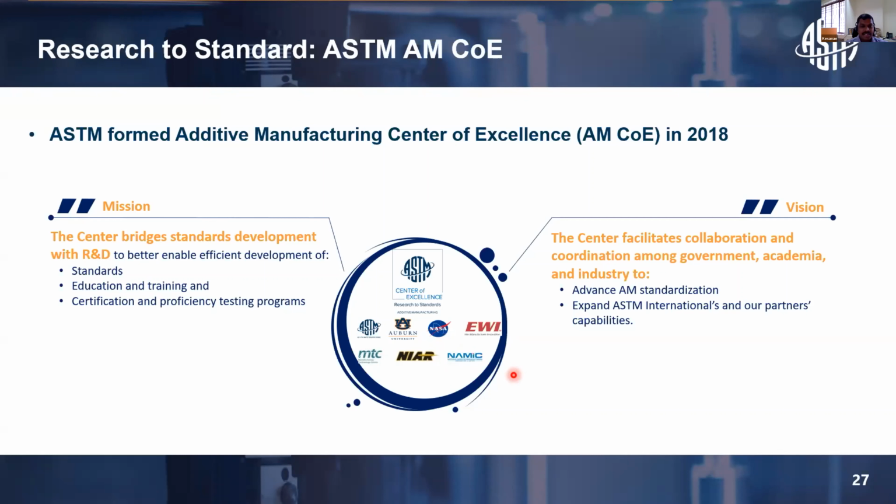Oh, nice. I'm also very much curious, I'm interested to see miniature samples, at the millimeter level, for AM. Is the standard out now, or is it still in progress? The standard is still under development. For that particular standard, there was a lot of research people have done to see how you can correlate the small or miniature tensile specimen properties with the corresponding E8 specimens.